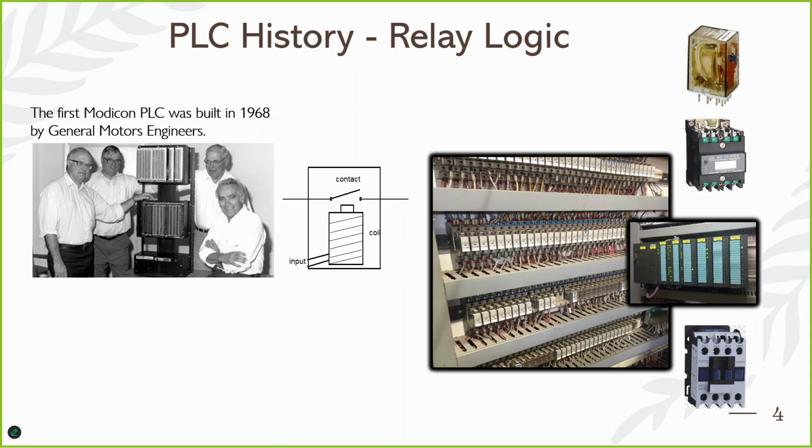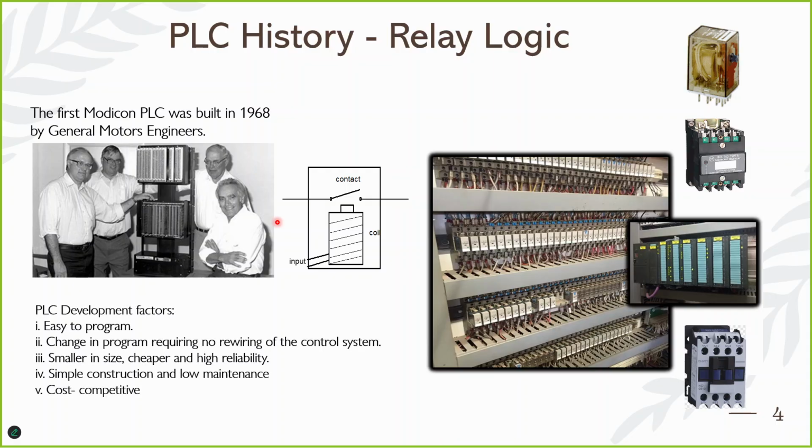And why were they developed? Basically, PLCs are easy to program. Of course, you can see from this image, it's easy to work with this rather than with all of this. Again, you can change programs easily and you don't need to rewire the control system. They are smaller in size, which automatically makes them cheaper to install, to maintain, to replace, and they have a higher reliability.